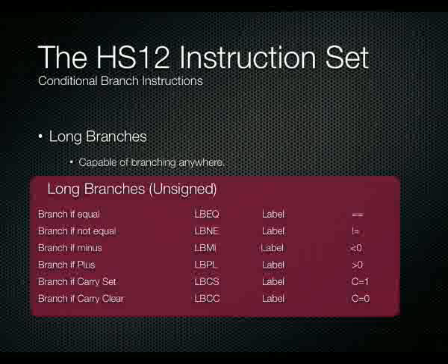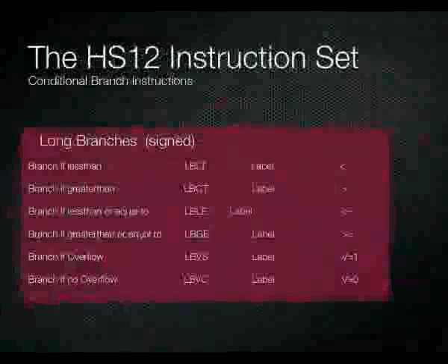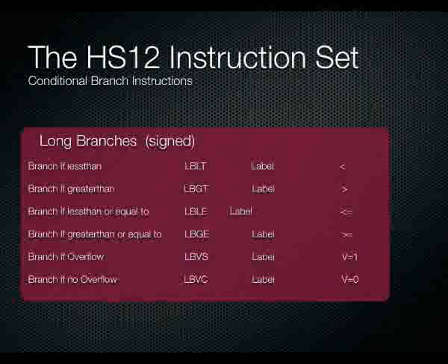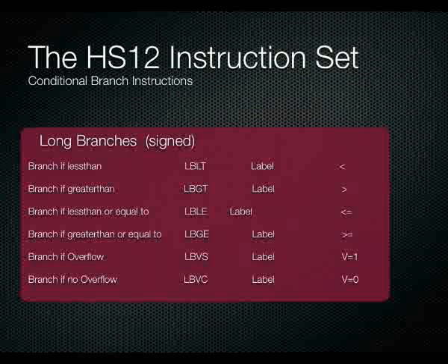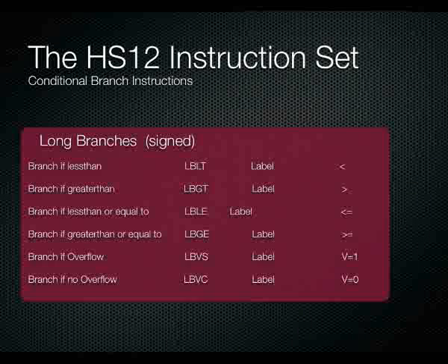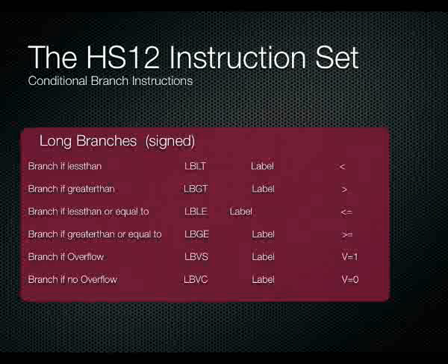So we have exactly the same ones we had with short branches, but now they're just the long version with an L in front of the mnemonic. And of course we have the signed ones as well, so we've got branch if less than, branch if greater than, branch if less than or equal to, branch if greater than or equal to, branch if overflow, branch if no overflow. So they're exactly the same instructions we had with the short branches, but now we have the long branch equivalent, which simply has an L in front of the instruction to say it's a long branch.